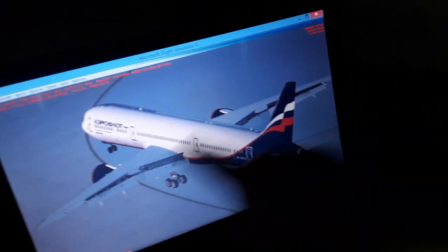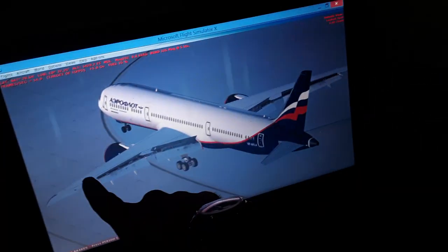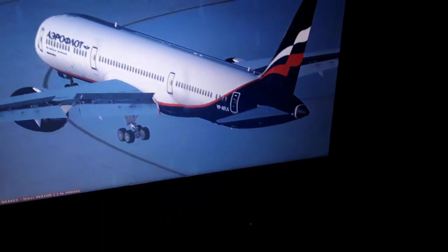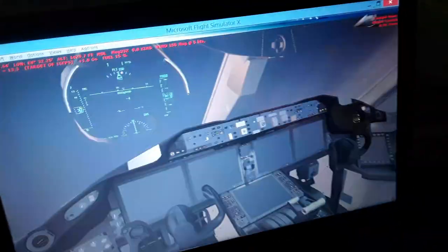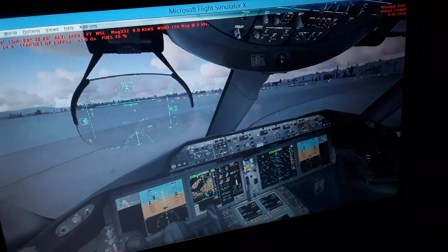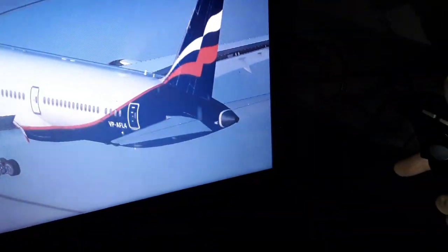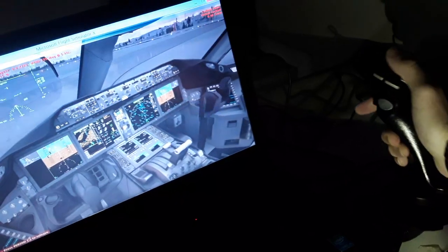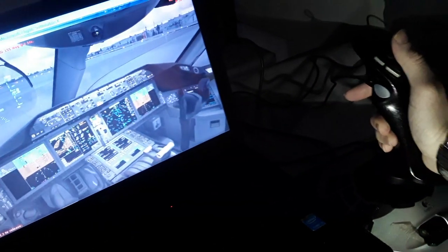We have also one more axis here from wingtip to wingtip. It's the pitch axis. We can use the elevator or stabilizer trim also. So the elevator is the side stick up and down like this. As you can see, side stick up and down. You can climb and descend moving the elevator. It's the side stick in the Airbus. You move the elevator up and down like this. It's the yoke in the Boeing. You move the yoke up, back and forth like this. So you can climb and descend. It's the pitch axis of the aircraft.